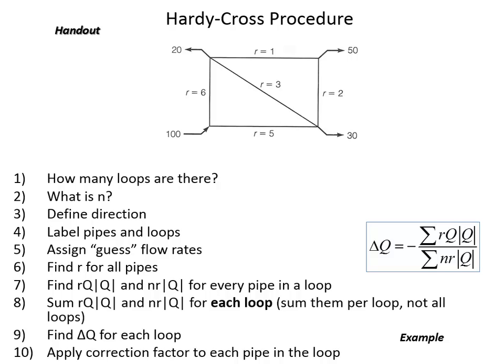So where it was 15 positive for the first one, I'd want to say negative 15 here. Except that I have a better guess already for what the flow through pipe 1-3 is. In this iteration, if you correct for things, it's not 15, it's 12.332. So I'm going to take this better guess that I have for that pipe, and I'm going to put it down into here. And so instead of negative 15, I'm going to say negative 12.332. All right?